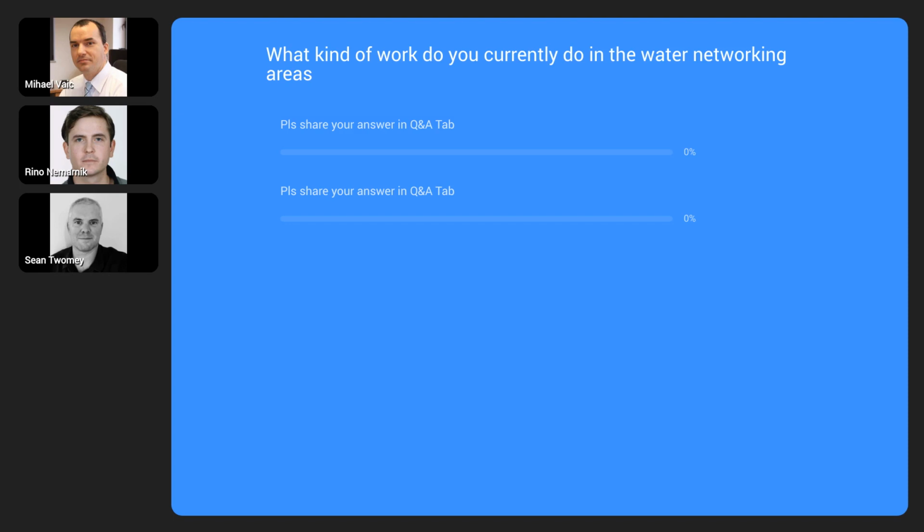What is a great thing is the possibility to communicate with WaterGEMS, because for water distribution networks we can both import and export the EPANET INP file, which means we can import and export to WaterGEMS as well. And regarding the storm and sanitary networks, we can export the EPA SWMM INP file, which can also be imported to SewerGEMS. And in the next version, which will come out by the end of this year, we also developed the possibility to import the EPA SWMM INP file, which can also be generated in SewerGEMS.